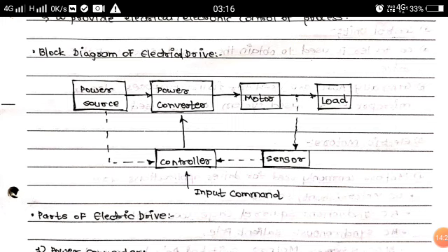And pumps are also directly coupled to the motor, but not many loads are directly coupled to the motor, because motors are available in standard sizes, and they also have some standard values of speed, and you can say some other parameters also. So those are standard, and the load may not be suitable for that. So there could be some power transmission element between the motor and the load. Examples: some chain drive, some belt drive, or gears, and like that. So many times there is a power transmission element between the motor and the load.